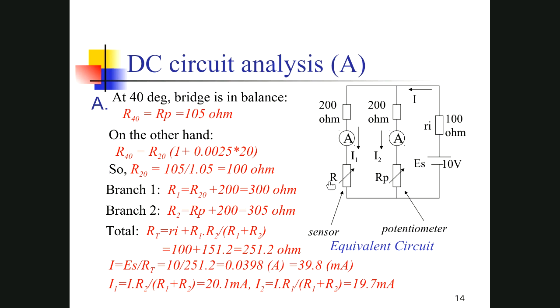So basically speaking, in applications, we can try to find different devices whose resistance changes with the environment. We have many kinds of materials. That's the sensors. Okay, so this is one branch. We can monitor the branch current using a small ammeter in series with this branch.